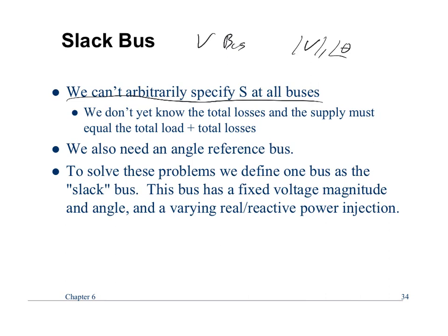So a good example in the real world would be a nuclear power plant, right? A nuclear power plant can dump out as much P and Q as necessary. The problem is that nuclear power plants don't like to shift their output all that much or that quickly. So even though it's a really strong bus, it's not a good bus from the perspective of being able to make up the difference. So you'd have to have a nuclear power plant with some additional generation that can swing up and down pretty quickly.